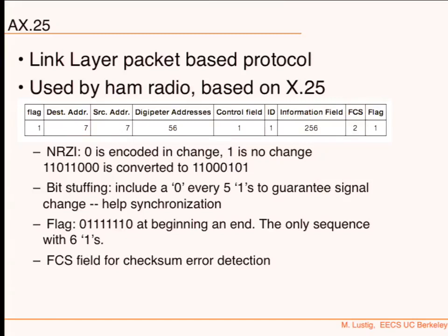One of the things that you could do in the project, for example, is change the modulation scheme from AFSK to MSK. So you can go at twice the rate, with almost the same bandwidth. Almost. Okay, so that's another option.